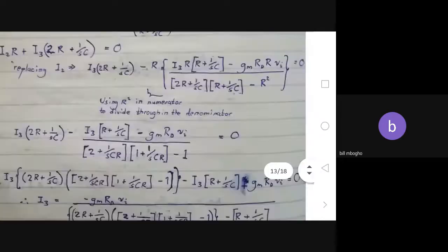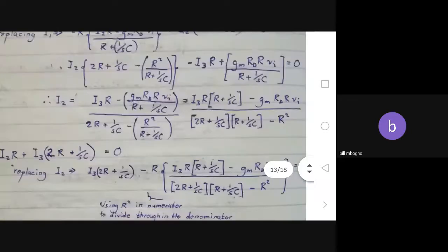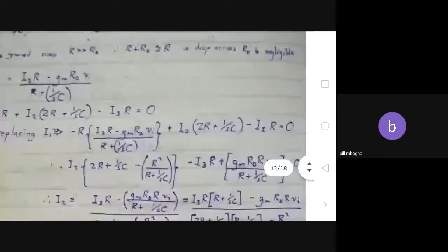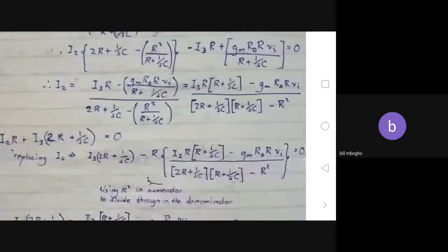And if you've noticed in all these calculations, I was using S, because I find that if you multiply such long equations, using j omega sometimes will confuse you, at the point that you have two j's multiplying, there's a negative somewhere, and those two j's are supposed to give another negative.